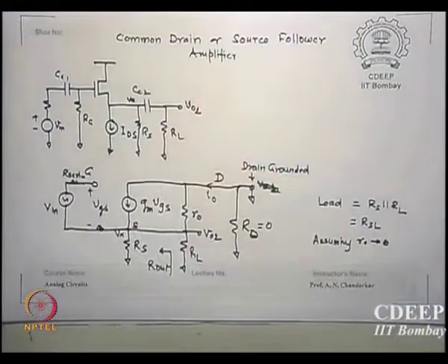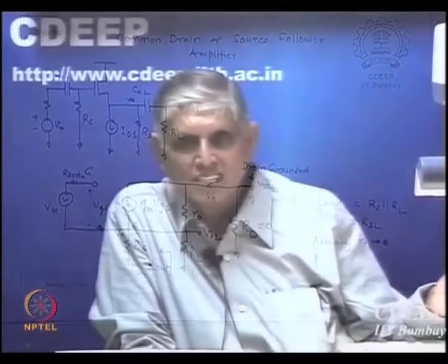So this is the equivalent circuit. What is the advantage of MOS over bipolar? One of the interesting things is that there is no connection between gate and source. There is no DC current between gate and source because of the insulator. In the case of bipolar, the base-emitter junction exists, and that means IB flows through both the emitter as well as the base. This fact is not there in MOS, so it is much easier to evaluate, because if there is a current common to two sides, then you have a problem to handle. So this is what we were doing last time, a source follower.